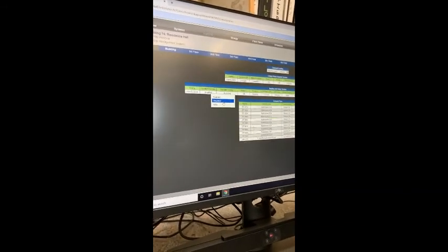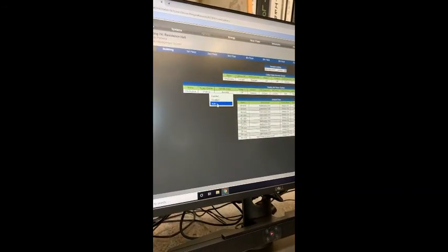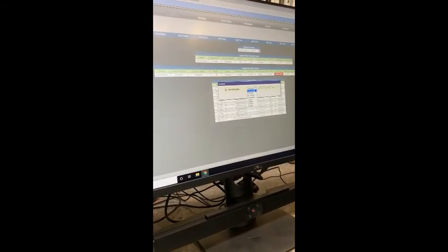So on these ones, anything that doesn't just say a set is an override. We can override it enabled, override it disabled, or release it to auto. When we override a point, you can give it a custom time for how long, which is handy. I always recommend doing that, even if it's for 2 days, so something doesn't get overridden and left, whether you're doing some sort of test.